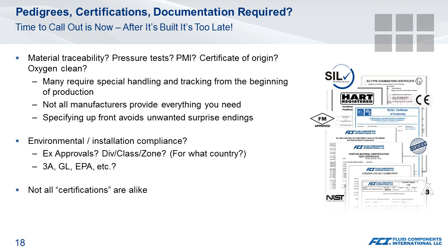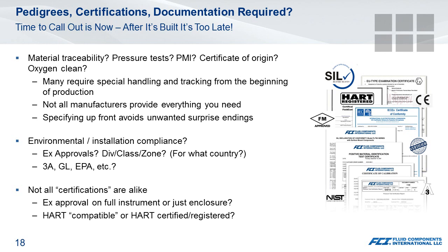So are you looking, for example, for just HART compatibility, or do you need a HART certified IO product with documentation to support it? And on some of the other things like declarations of conformity, other conformities you're looking for, is independently certified required, or is self-certified adequate?